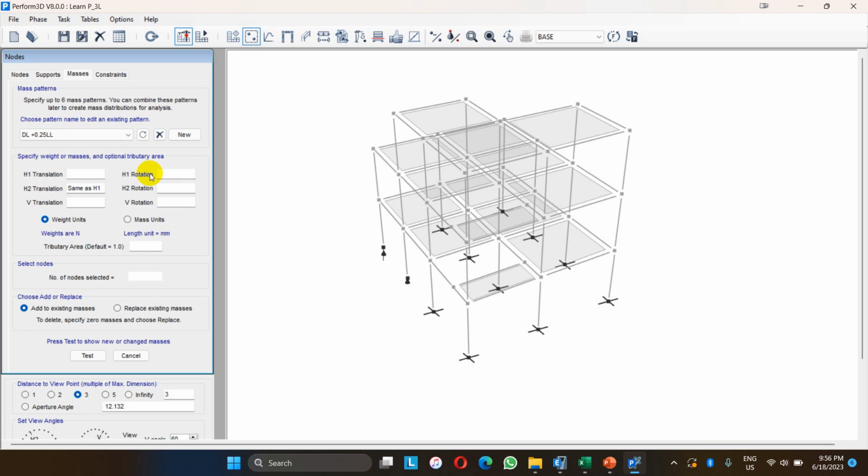This can be applied in different ways. The first way, the simple way, is to import the structure from ETABS, and the mass source can be assigned to each node of this structure. And another way is to insert the coordinates, and we have to calculate the seismic weight of the structure or lump mass. We can say it's lump mass at the story level. We have to input the coordinate here at each story level and input that mass system, a lump mass.